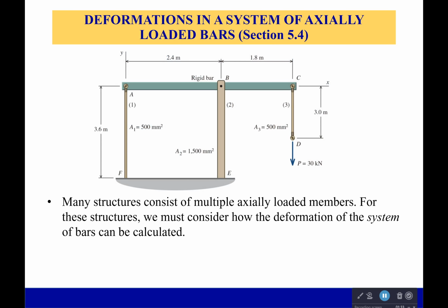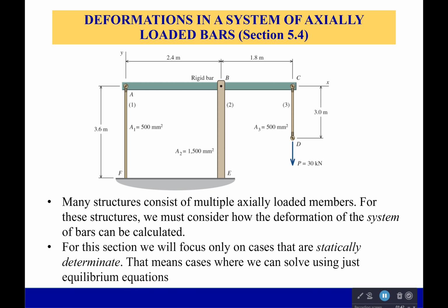Okay, so many structures are very similar to this. They're going to have multiple axially loaded members, kind of like this one right here, which we're going to work through. And so we have to figure out how we can figure out the deformation of the system of bars. Now, in some cases, it will be something called statically determinate. That says simply that we can solve it using just our equilibrium equations. We don't have to worry about anything else. Our equilibrium equations, those will be enough.